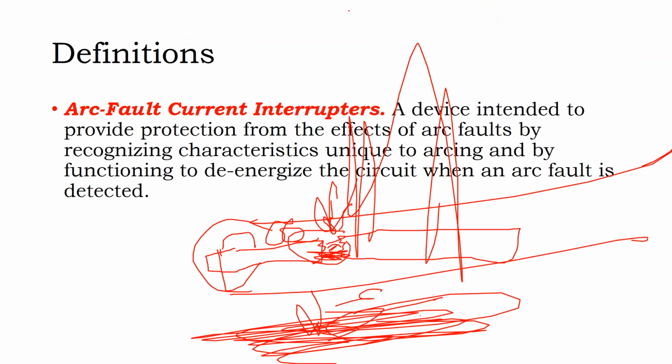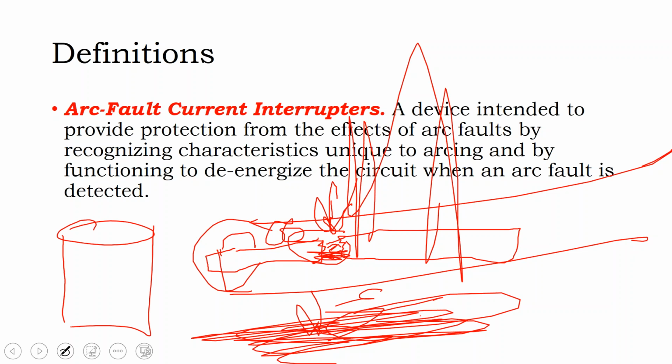Now, arc fault currents are harder to detect. It used to be that in solar design, we just didn't detect them, because they're more difficult and expensive to detect, and the arc fault detection circuit technology was not developed for the solar industry. But I can tell you where a common arc fault is: in the MC4 connector housing.